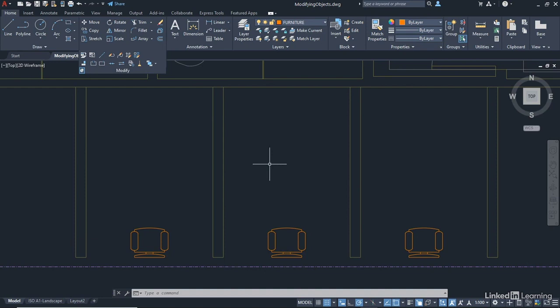Now, I'm going to use stretch and lengthen to improve what we've got going on down here, because at the moment, there's our grid line and there's our partition walls. And we want our partition walls here to meet up with that grid line. It's just easier from a measurement perspective for the guys on site. They can then measure these internal walls out to the grid and obviously create the internal walls for our hot desking cubicles. Now, we're going to use stretch and lengthen to perform the same workflow.